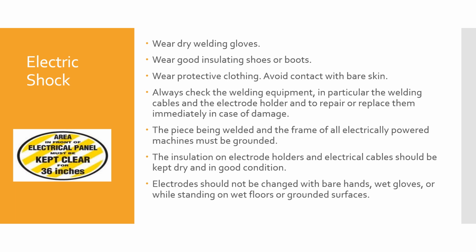A lot of this is just common sense, but we need to address it. If you have wet clothing or you're working in water, your electrical cables should be kept in good and dry condition. So this addresses quite a few of the items that we really need to be cognizant of when welding, and the electrical hazards that can come with welding.